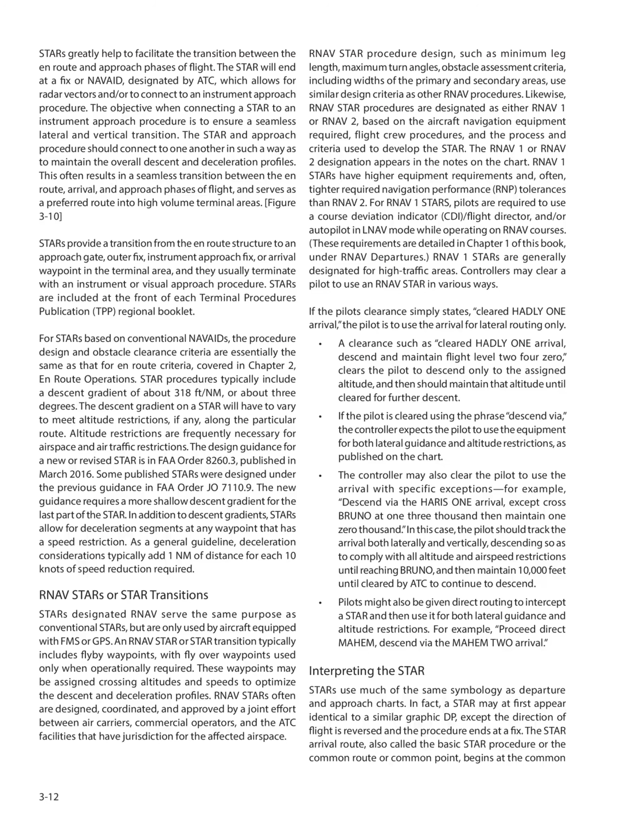STARs greatly help to facilitate the transition between the en route and approach phases of flight. The STAR will end at a fix or navaid, designated by ATC, which allows for radar vectors and/or to connect to an instrument approach procedure. The objective when connecting a STAR to an instrument approach procedure is to ensure a seamless lateral and vertical transition.